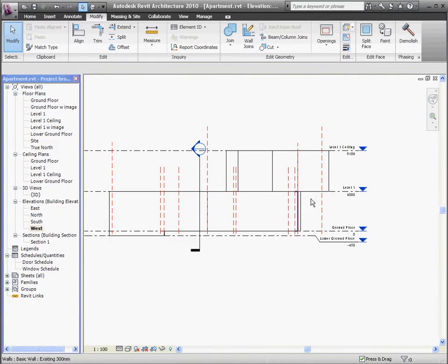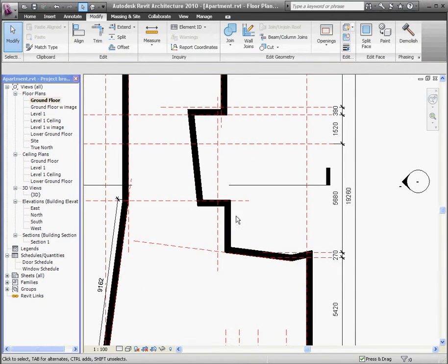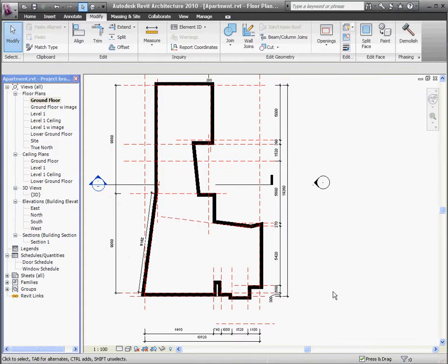We don't need to make a separate level for the ceiling below level 1. And that's going to be probably the trickiest thing to model, but we'll do that based on level 1. And then the extra roof that pops up over the part of the living area on the ground floor, over this area, you've got a roof that pops up and has a different ceiling height. We'll tackle that when we get to it. We may need to add a level in for that, but we'll probably be able to just base that on level 1 as well. So that's it for the levels for now.